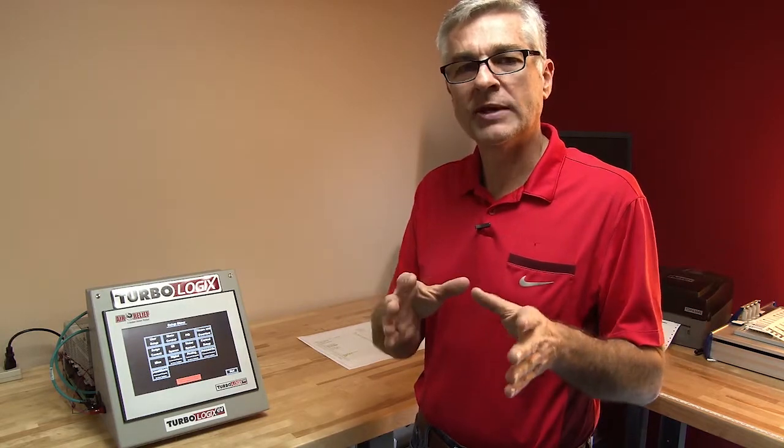Now, we always recommend that you go to your nameplate on your compressor and your motor and you write that detail down so that you can program that in and make it more unique to this compressor and easily accessible for our service people or your individuals that are working on the machines.